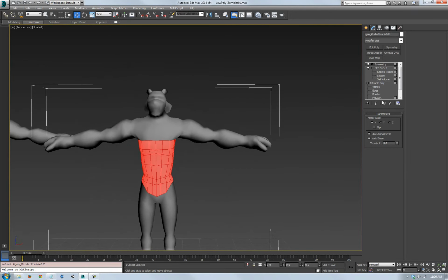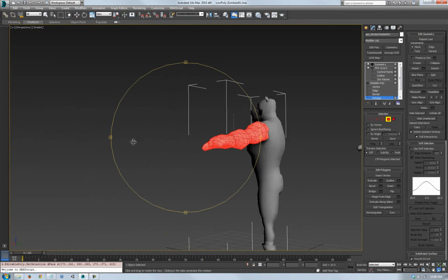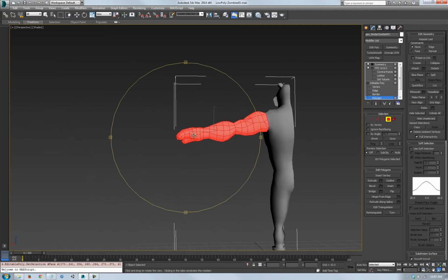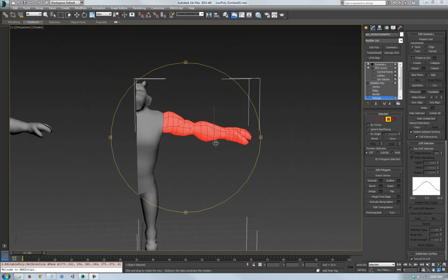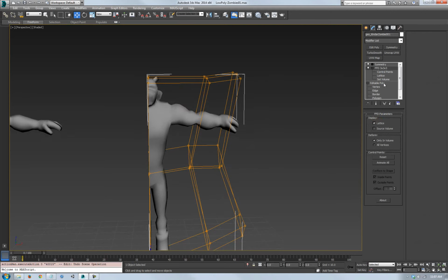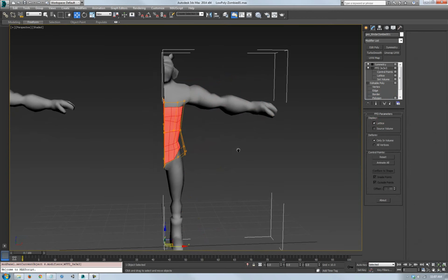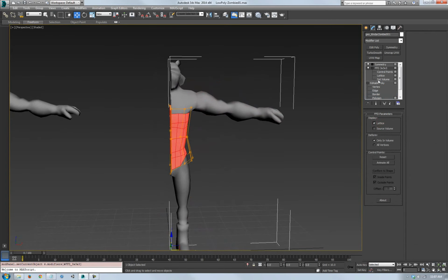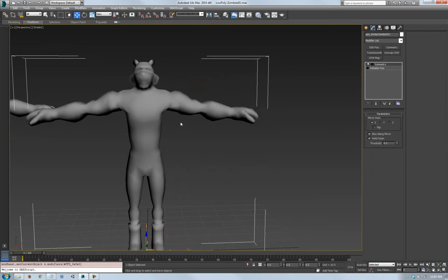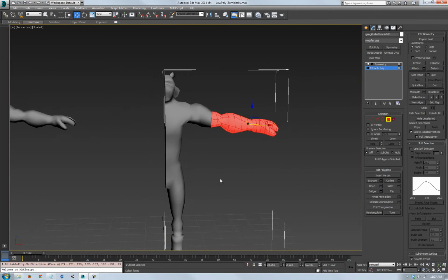Now that we've done with this, let's go back into the polygon selection. It's going to select the arms. Make sure I've got all the parts that I want to select. Yeah, that should do it. Alright, and as with before, well, oh, oops. Yep, I ended up doing something I should not have done. There. Alright. So now that I've got this FFD on here, once I'm finished and I'm ready to go on to the next step, all I got to do is just collapse it, and we've now saved the changes that we've made. So I'm just going to go back in, redo the arms.